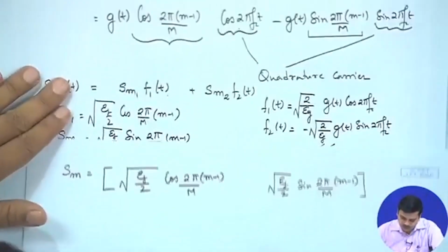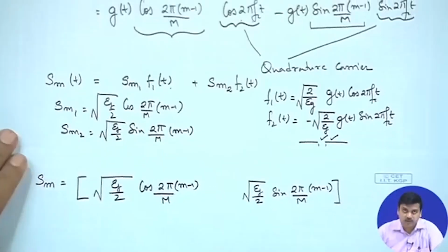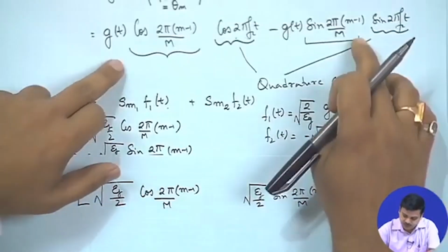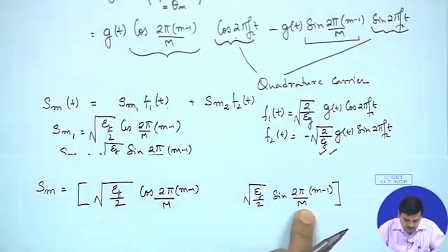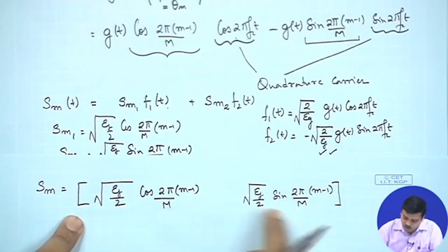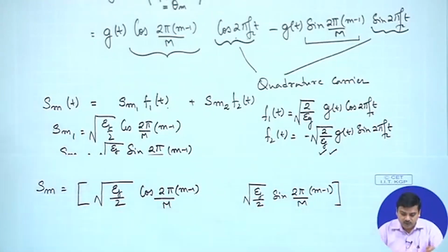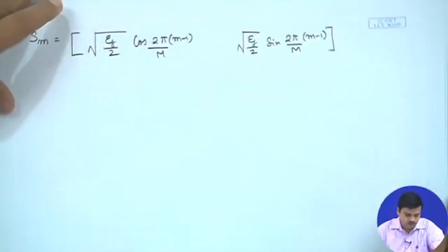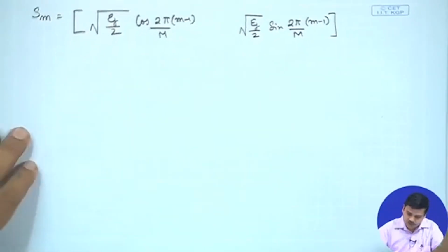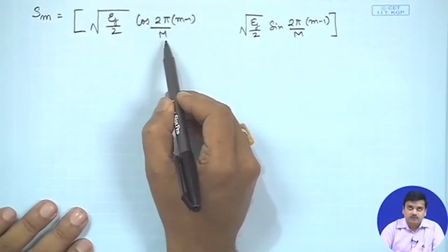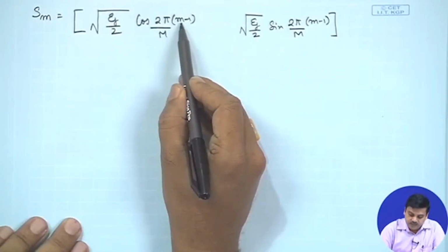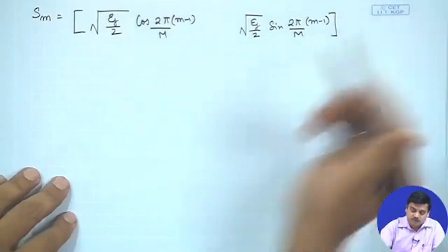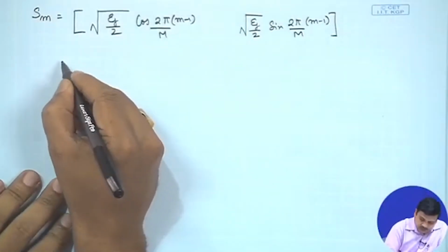So, that is it. If you look at this whole setup that we have created, from this expression we have been able to create the vector notation that we are generally interested in. Once we have this vector notation, we can use our typical vector rules to proceed with the computations for this particular signal model. As you choose a value of capital M and change values of small m, you can create all sets of these coefficients. As we did for pulse amplitude modulation, we would be interested in the signal energy.